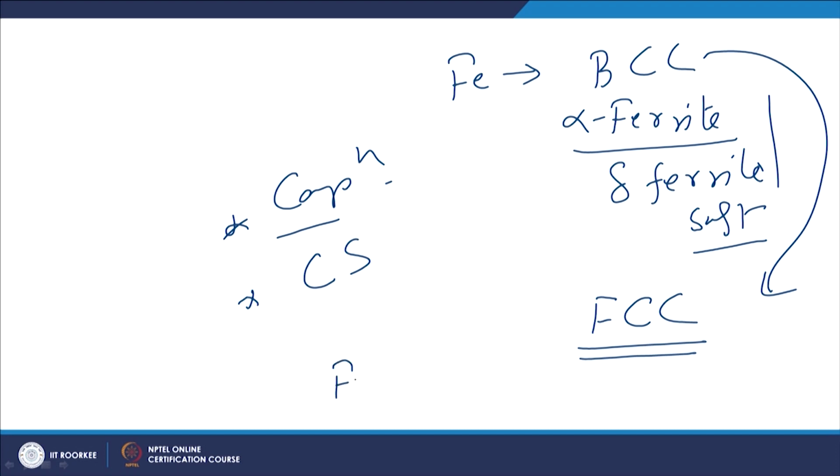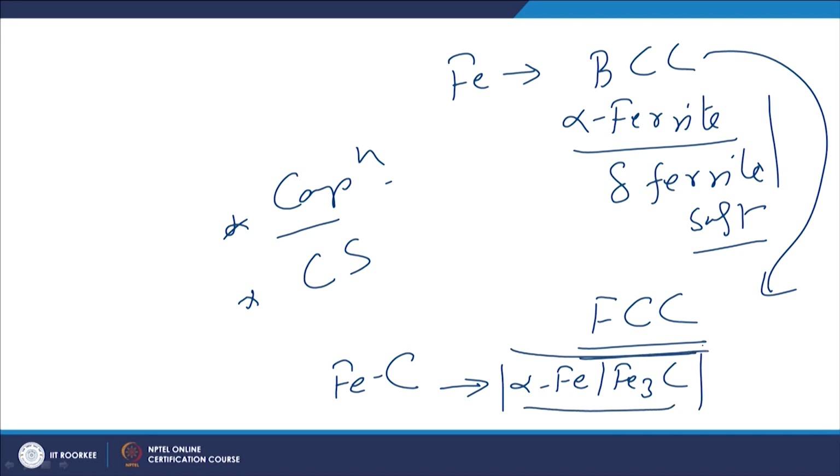Similarly, for a given composition of the iron with the carbon, we may have the alpha ferrite or iron carbide, and when such kind of the mixture is subjected in very controlled way for the phase transformation, we may get the martensite, which is comparatively harder and brittle. So, this will be having altogether different kind of the crystal structure like BCT structure.